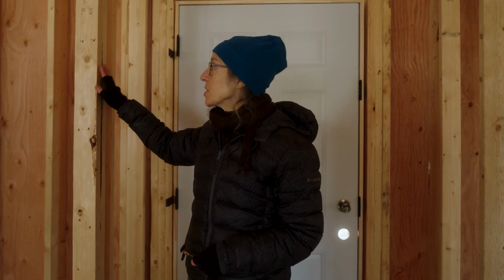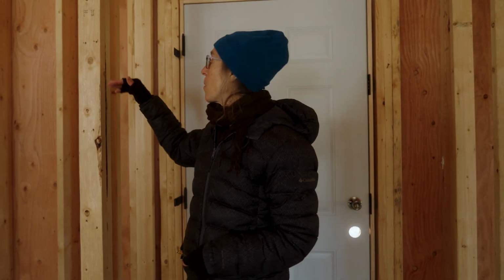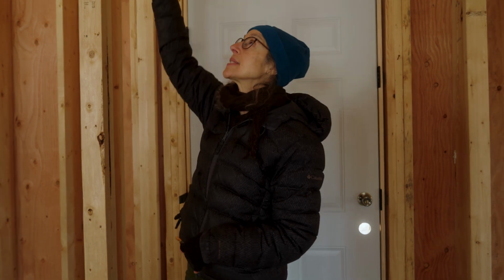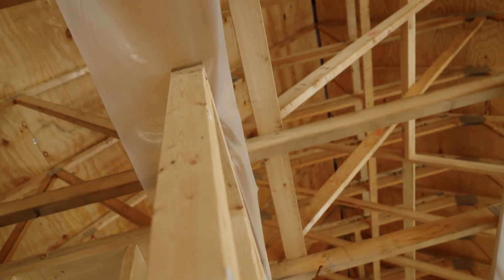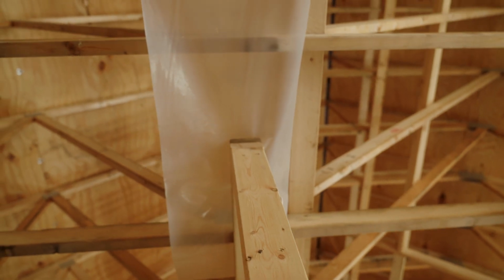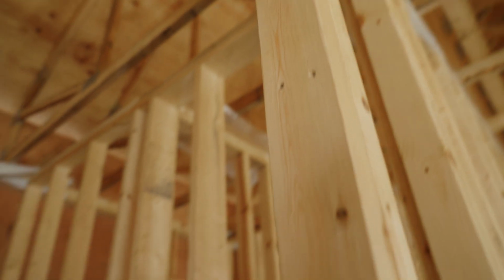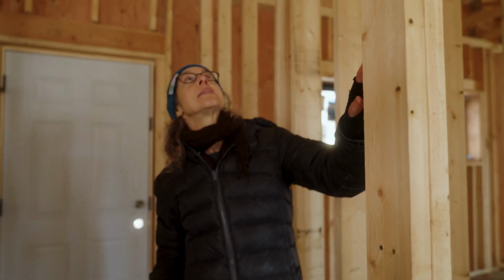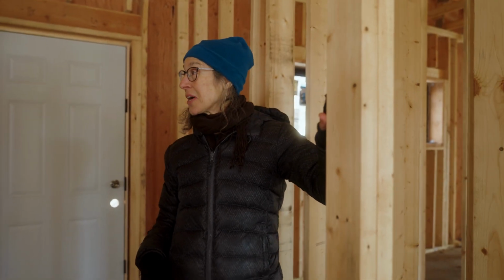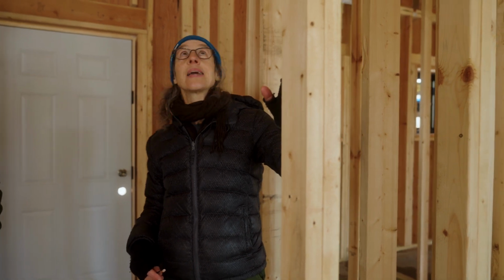The interior partition walls, so this is an interior partition wall, where the interior partition wall joins the plane of the ceiling, which is formed by the roof trusses, we want a continuous air barrier and vapor retarder at that level. And what you're seeing here is something very simple that I learned about years ago in classes, which reminded me as a designer to talk with the builders about having that poly on site.